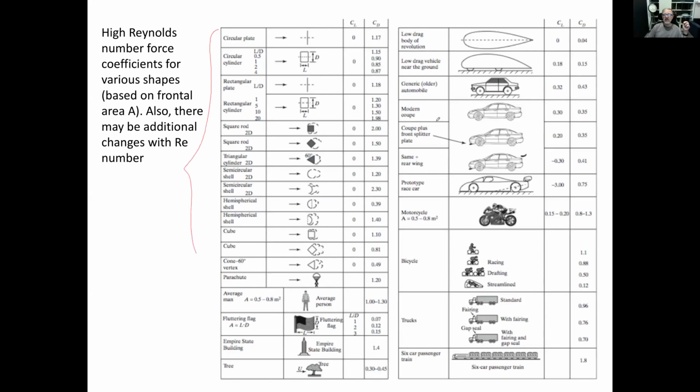And then the others are three-dimensional, but there is, for example, a parachute here. And look at the flat plate. Here it shows 1.17. Now you start adding thickness to that, then the flow separation becomes less because it reattaches. So the drag eventually, if it's getting longer, the drag coefficient goes down. Very interesting. Okay, this is a rectangular plate, 1.8.